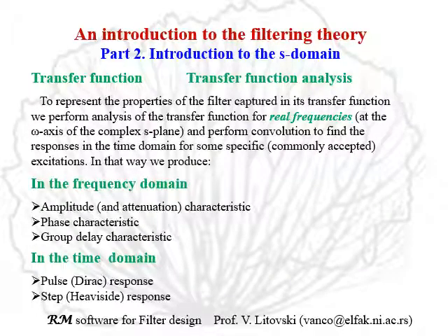To represent the properties of the filter captured in its transfer function, we perform analysis of the transfer function for real frequencies at the omega axis of the complex S plane, and perform convolution to find the responses in the time domain for some specific, commonly accepted excitations.